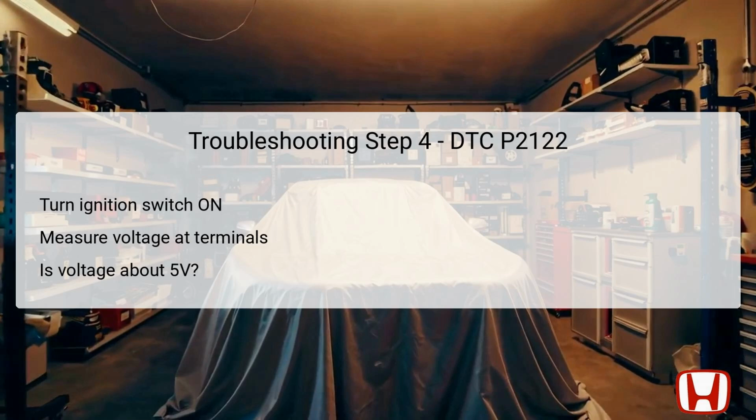However, if the reading deviates from this expected measurement, it directs the technician to investigate further. Low voltage signals at this step could suggest wiring issues or sensor malfunction, warranting further troubleshooting to ensure accurate diagnostics.